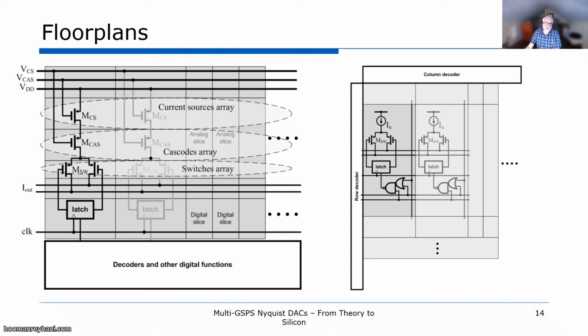High-performance DACs are constructed from large arrays of unit circuit cells that must be meticulously routed over significant silicon areas and operated synchronously with picoseconds level precision. Consequently, routing and placing each constituent block to minimize interconnect parasitics and mitigate spatial mismatch is a complex combinatorial optimization puzzle with many trade-offs and dangerous traps. Implementing robust floor planning and layout techniques is therefore critical to minimizing these physical impairments.